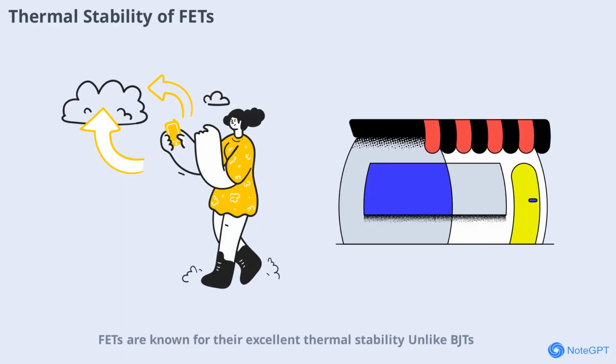FETs are known for their excellent thermal stability. Unlike BJTs, which can suffer from thermal runaway, FETs tend to self-regulate as temperature increases. This property makes them more reliable in environments where temperature fluctuations are common, such as automotive and industrial applications.